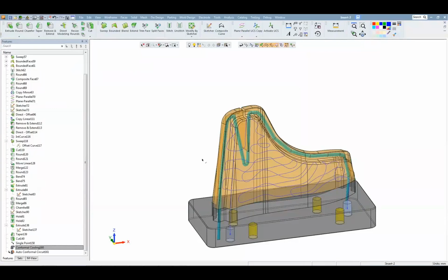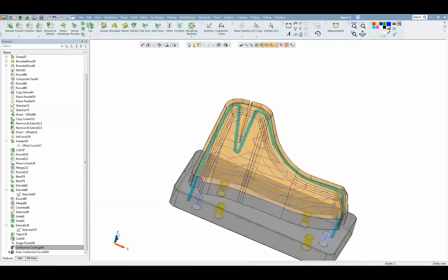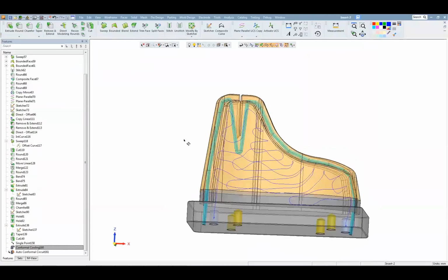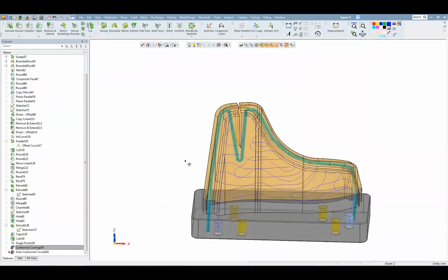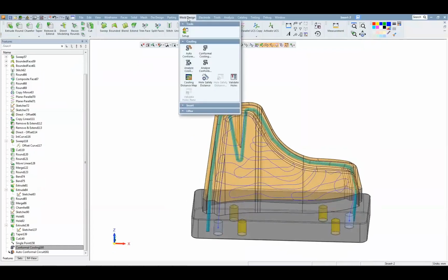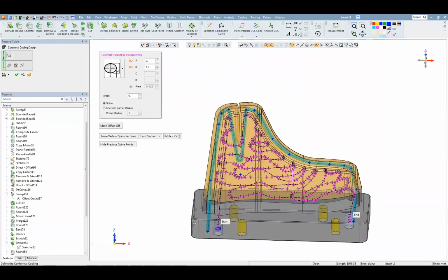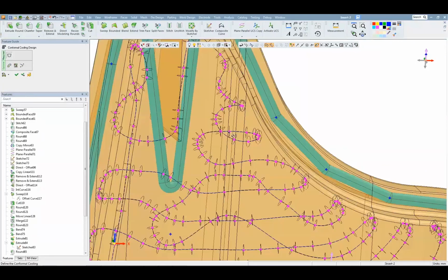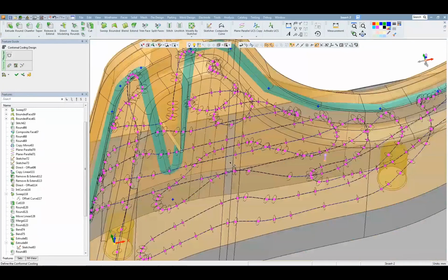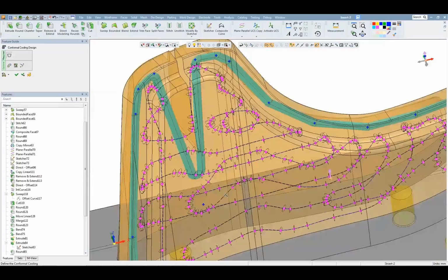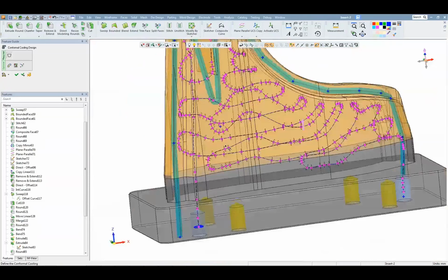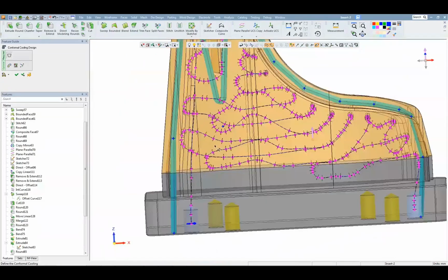And that's it. That's the time it takes to create the cooling path for this entire part. You can see how complex it is, and you can imagine how hard it would be to create that manually. So then we select that as an input for the conformal cooling tool, and very quickly we get all the sections in place. They are all aligned correctly for 3D printing, so standing upright. And it's really that simple. It's a few clicks and you have it.